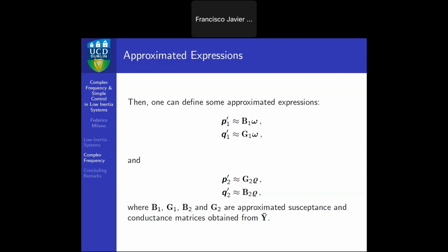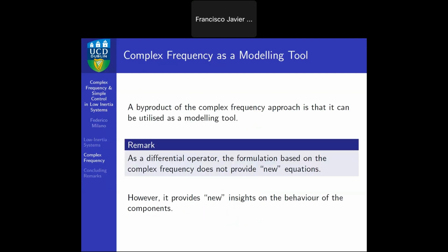At that point, you can equally impact omega and the voltage using equally P and Q. And if the network were more resistive than reactive, then you better control the frequency through the reactive power, which is kind of a strange thing to say. But if your network were for any reason more resistive than reactive, then you should do that. Okay, probably it is also very well known, but it's confirmed by this analysis.